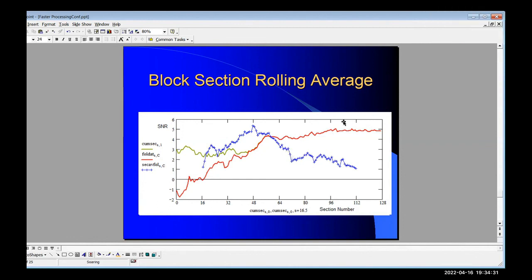So a further comment about RFI, Peter, is that along with scintillation, you can probably get SNR variability just due to broadband noise fluctuations within the band, where there are no identifiable narrowband interferers, but the entire band can get broadband interference that fluctuates over time during the course of your observation. And that will also drive variability in your SNR.